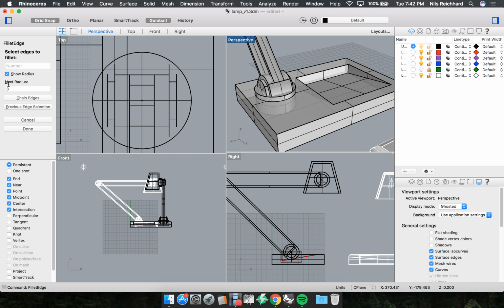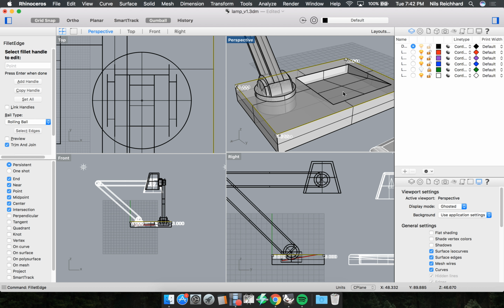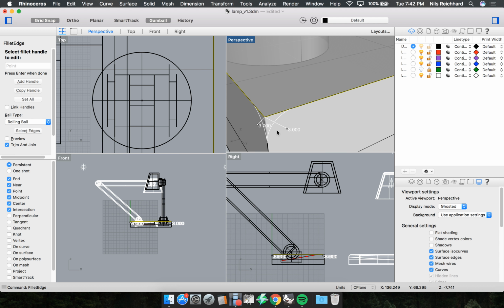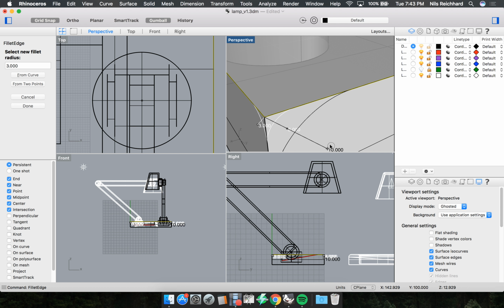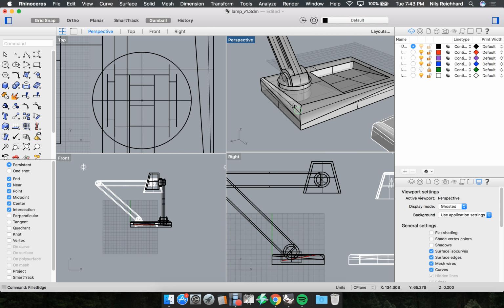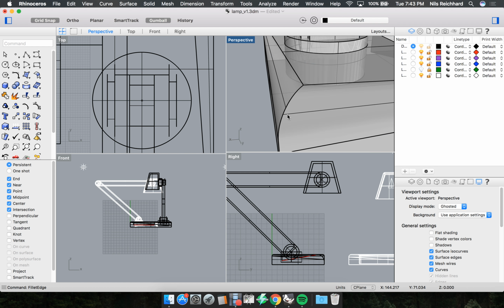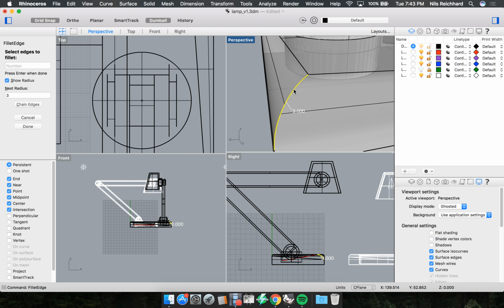So we got a radius of 3 here, 3 here, 3 here, and 3 here. And then I can also modify by hand by adding a little bit more radius here and a little bit more here. So I will give it a little bit a different shape, a more modern shape. And I can do some fillet again. Let's see, from here to here, so it's very smoother.